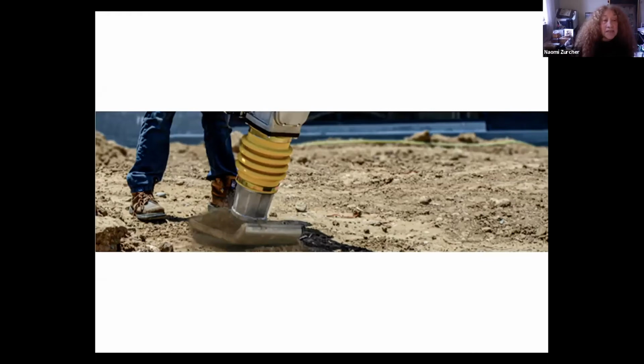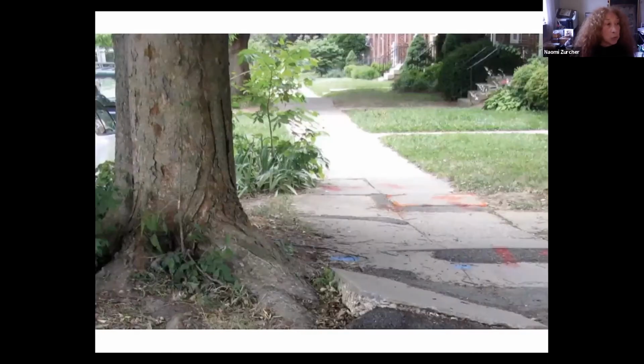First, a sealed compacted substrate encourages root growth exactly where it will have conflicts with surrounding infrastructure, just under the surface of the paving, where condensation accumulates and pockets of air exist. Roots will explore and expand in these spaces, generating enough mechanical force to accentuate any structural or material faults present. Tree roots do not damage infrastructure. Rather, they take advantage of flaws in that infrastructure.